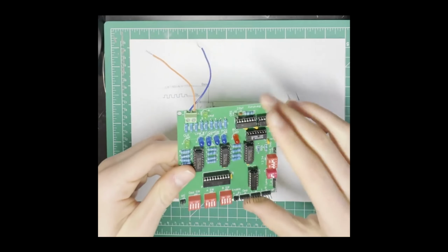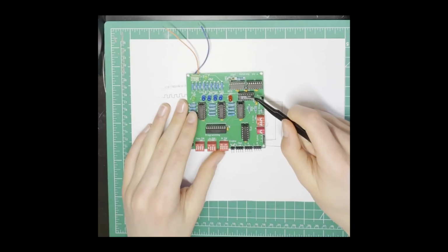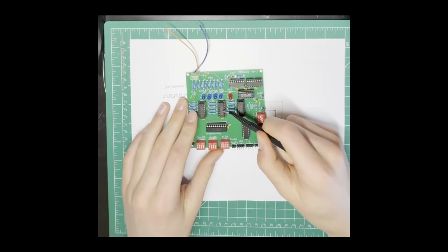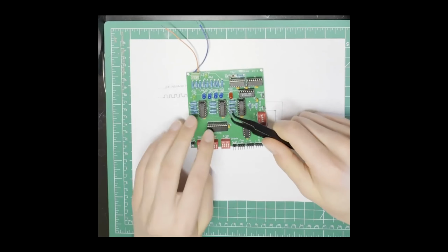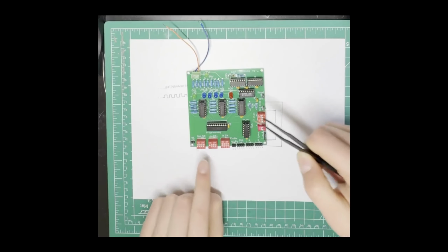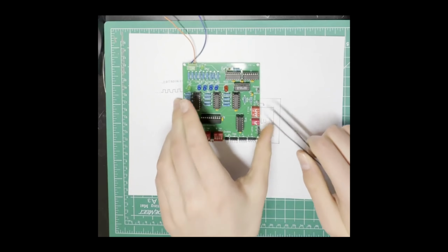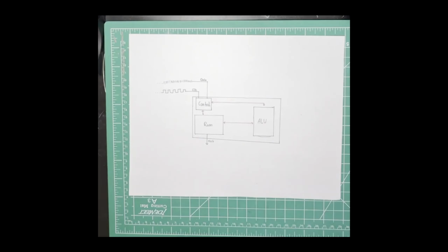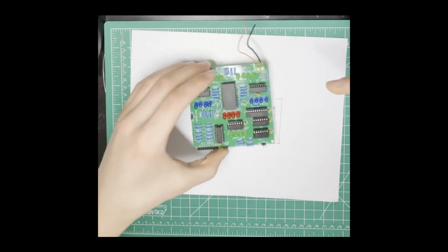And so the clock goes into the counter, the counter's output feeds into the RAM address, and the RAM now spits out a number that is programmed via these DIP switches right here. Now, that output from the RAM feeds into the CPU itself.